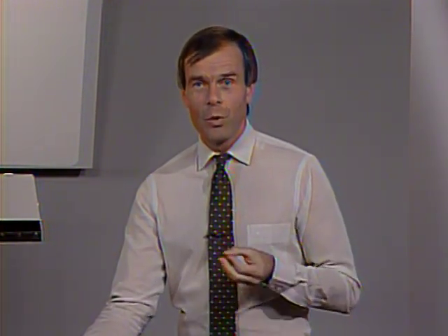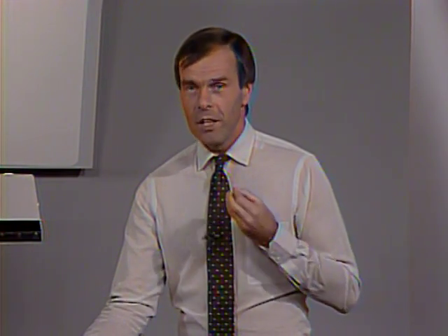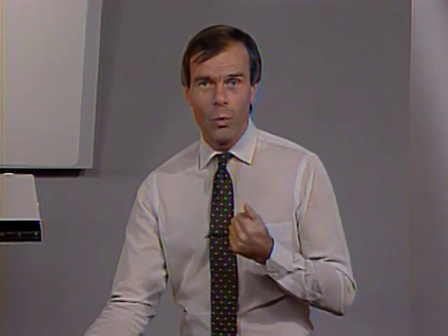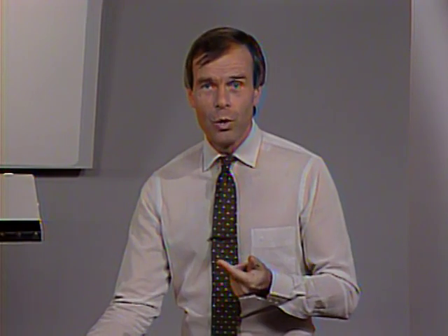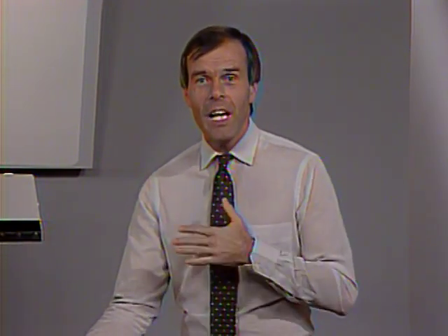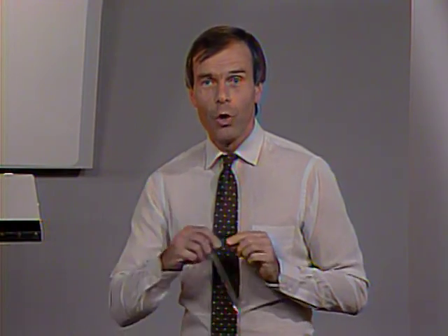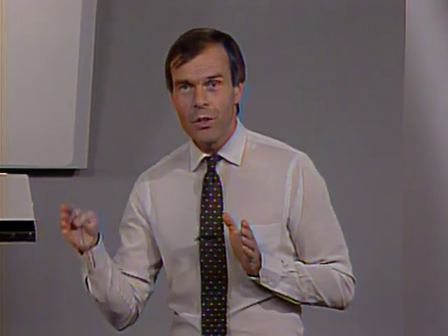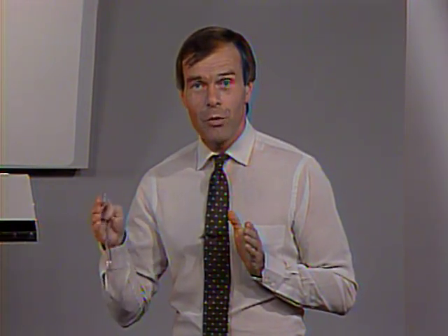In linear analysis you would typically solve the dynamic response equation in mode 1, then the one in mode 2, then the one in mode 3, and like that you sweep over all the generalized degrees of freedom, one after the other, for the total response from time 0 to the end of the response time that you're interested in.